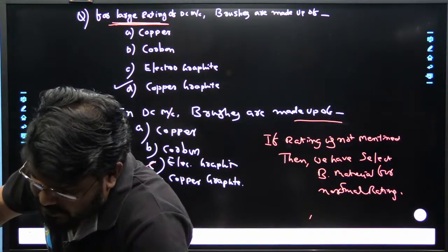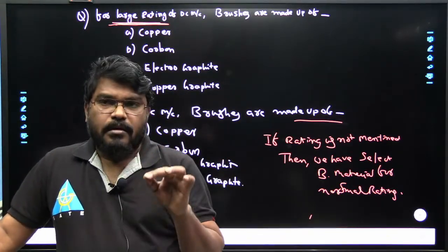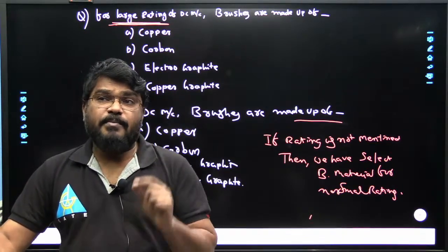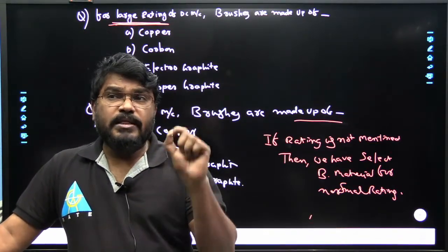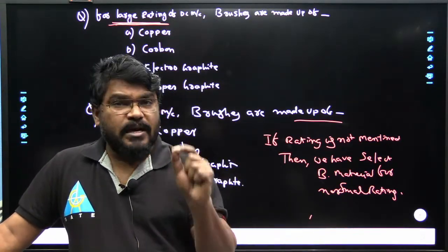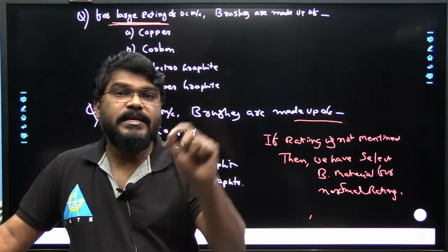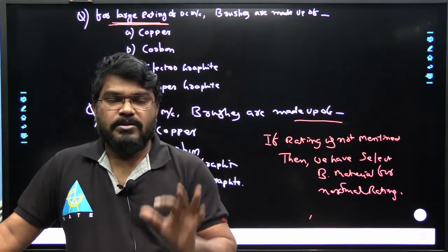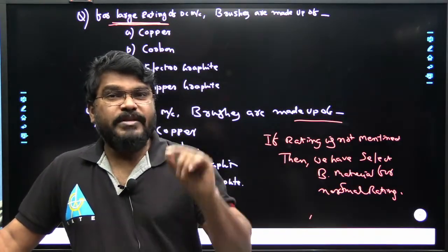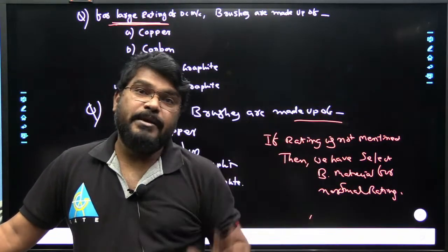In the pole shoe, is the flux AC or DC? In the pole shoe it is AC. What is the reason here? There is one more winding, that is the compensating winding. The compensating winding is used in the DC machine to neutralize the armature reaction effect. This compensating winding is placed in the pole shoe and connected in series with the armature winding, to neutralize the armature flux.